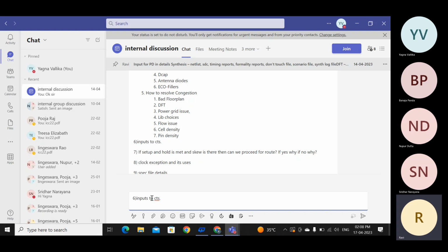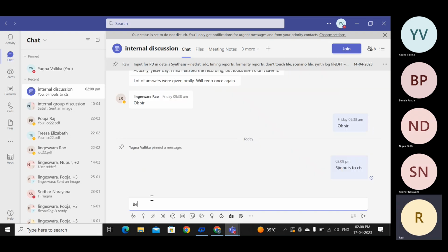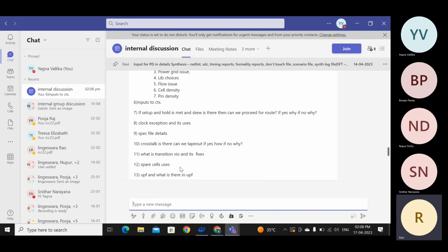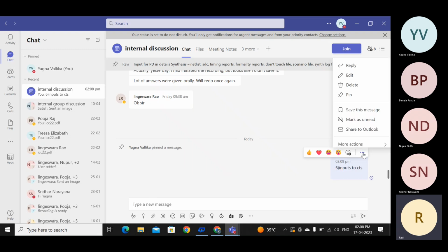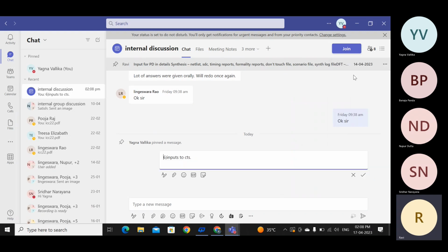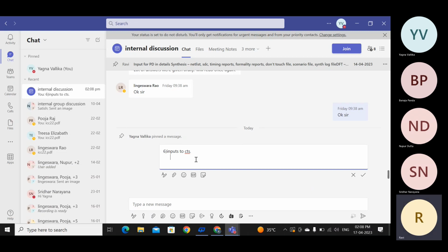Okay. So inputs to CTS. Before you do clock tree construction, you have to review your database and make sure your CTS mux placement and all the pre-placed cells, in terms of the clock tree, are proper. You should ensure that before you do CTS, all your clock cells, all your CTS cells, are of type clock cells, because if you have a data type cell in your clock tree, then all the constraints you give in terms of adding CTS cells would not be properly honored sometimes. Okay, so ensure that is taken care of.